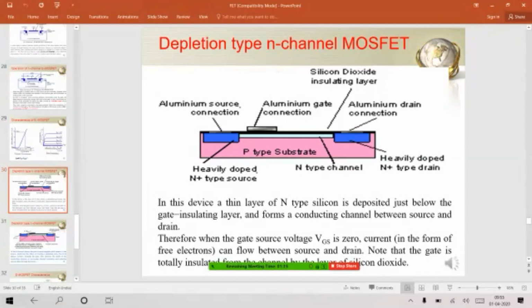That is the thing. This black colored layer shown here is the oxide layer or insulating layer, what I discussed in the previous case, right? Silicon dioxide insulating layer we call it. So this is the gate. Your gate is sitting here, where you have to apply the voltage and see the conduction in the device, right?